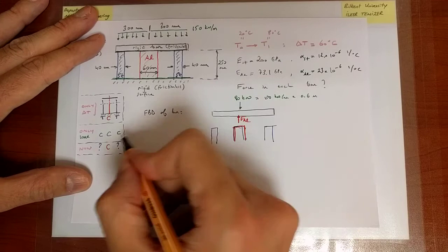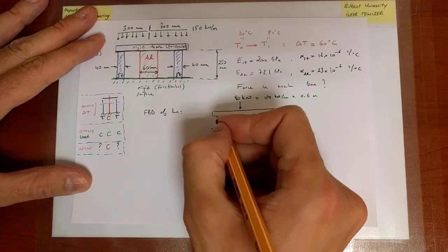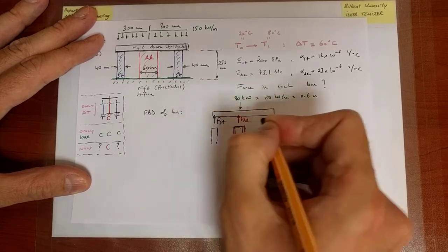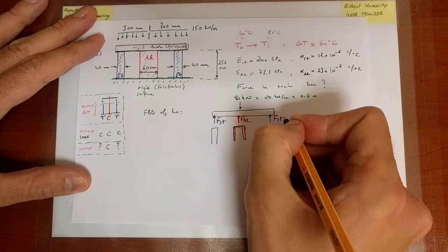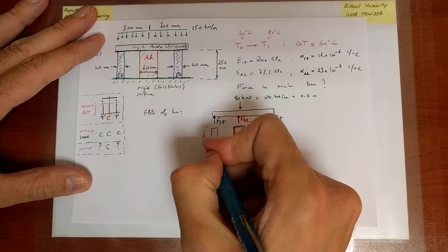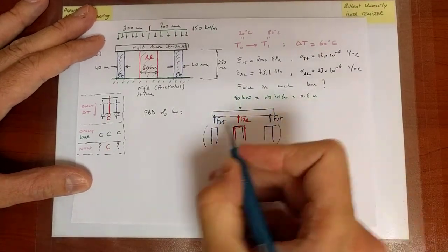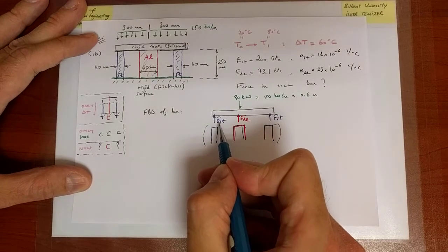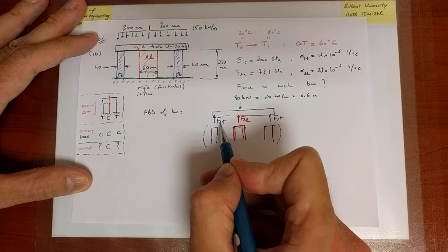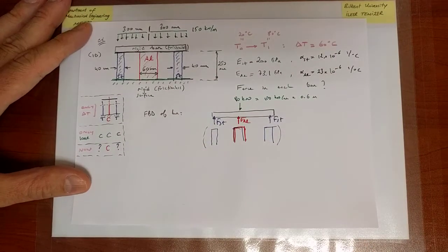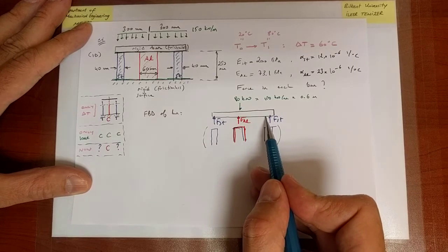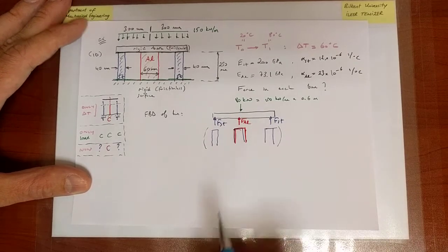So now, how about the steel, forces on steel? I don't know in which direction they have to come out to be. I'm going to assume that they come out to be in that direction. Okay. Now, I have no expectation on the bars, so whether they're tensile or compressive. If they come out to be positive, it means they were also under compression, certainly plausible. But if they're negative, it means my assumption was wrong. I should have assumed they were in the other direction. So if they were in the other direction, it means I'm pulling on the bar.